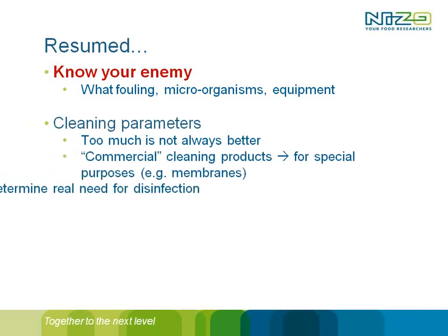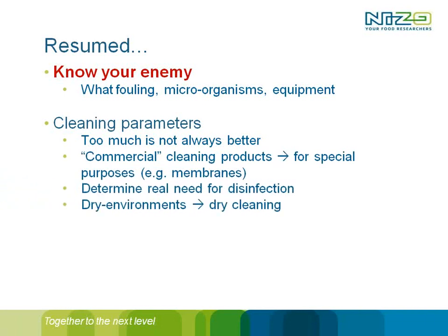If you talk about the cleaning parameters, as Arjen told, too much is not always better. Adding more caustic or alkaline is not always a better solution. Commercial cleaning procedures are products. They're good for special purposes like membranes. You can use them in other situations as well. It's a cost issue, and you have to decide for yourself whether you want to use them or whether you stick to regular alkaline or acid.